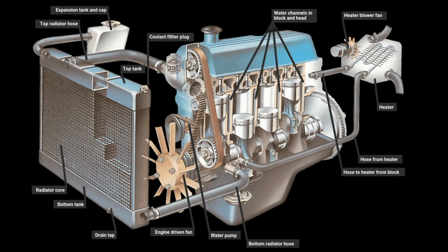2. Radiator. The radiator acts as a heat exchanger for an engine. It is usually made of aluminium, with lots of small diameter pipes with fins mounted on them. It exchanges the heat of hot water coming from the engine with the surrounding air. It also has an inlet port, outlet port, drain plug, and a pressure cap.